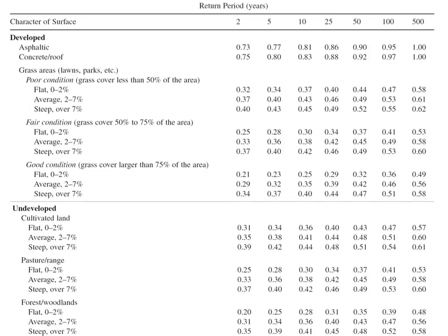And so in a 2-year storm, what they're implying is that 27% of the rain is required to wet the surface, and then the remainder is runoff. But in a larger storm, in this case the 25-year storm, only 14% of that rain is required to wet the surface, and then the rest runs off. So what these differing C values as a function of return period are referring to is the fact that it's not the surface itself that is changing, it's just that on a relative basis, less of the precipitation is required to overcome those initial abstractions. All right, so that's one effect I wanted to point out.